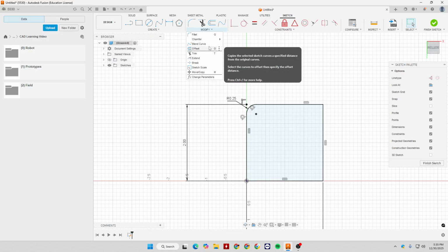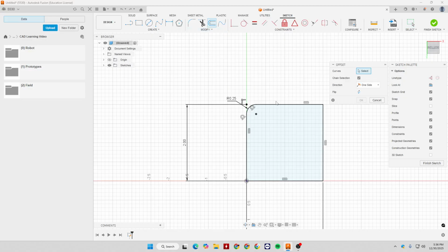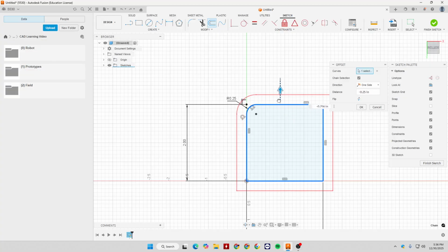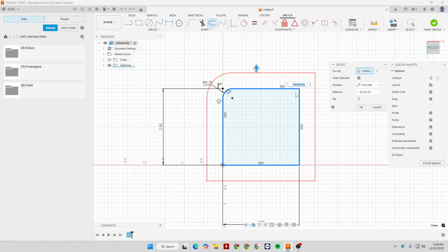The next one is the offset tool. You can see this being used pretty often if you're trying to create a 3D print, a screw hole, kind of reinforce something. If you're trying to encompass it entirely, you can select your curve, which will be a closed shape, and then the offset from that. So it'll be equidistant from all of those points on your curve.